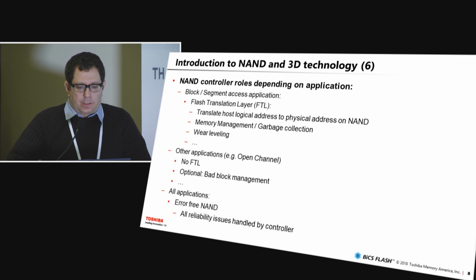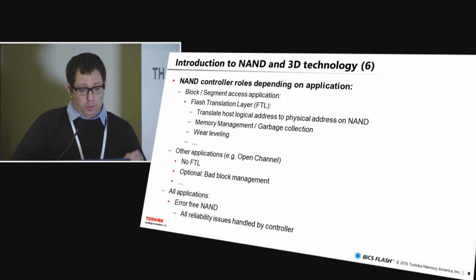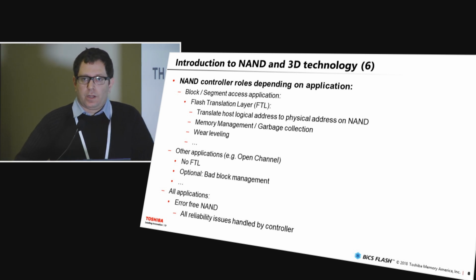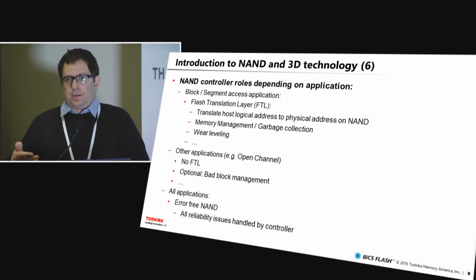In other applications, for example, open channel, you would go without the FTL. Mainly what all applications would still have is a layer that is responsible for the NAND reliability. And this is what I mainly want to talk about. For all controllers, you want to represent to the system, to the FTL, to the host, an error-free storage.